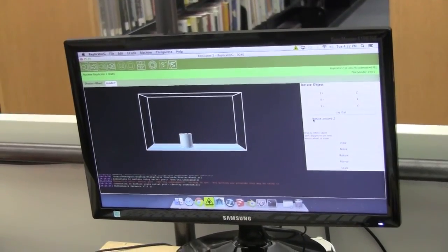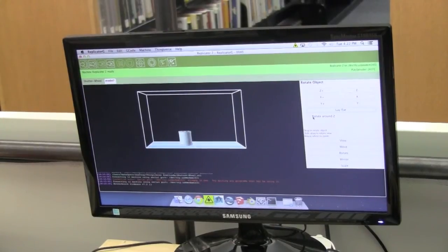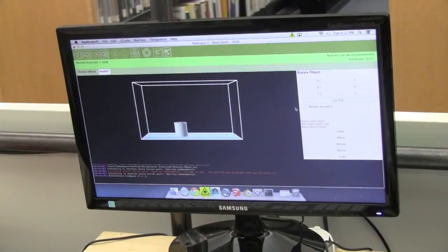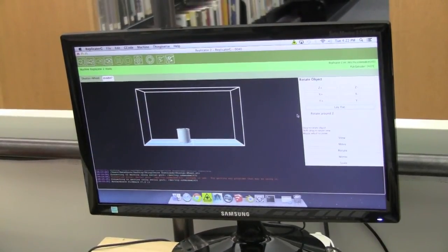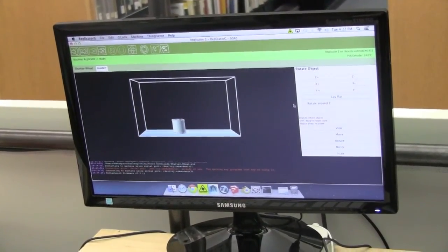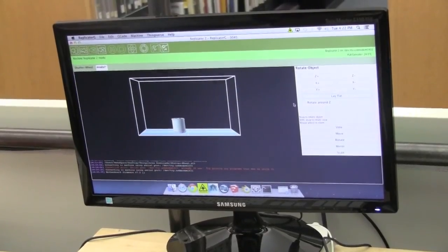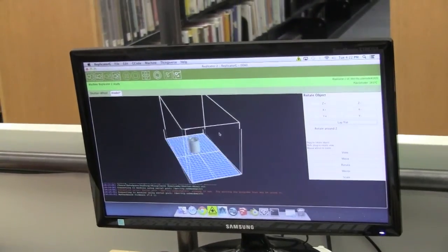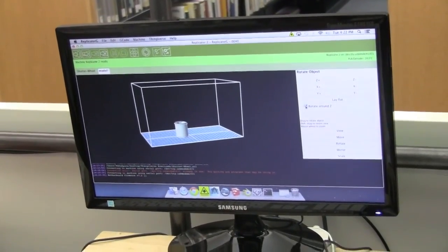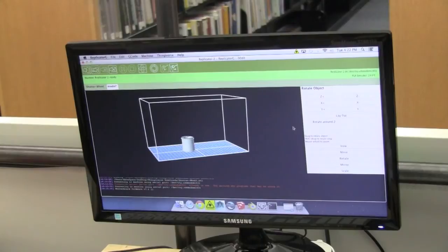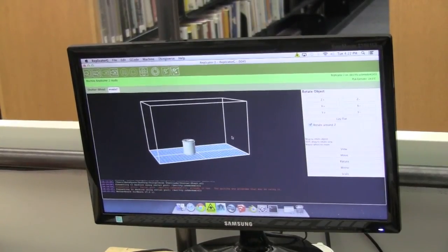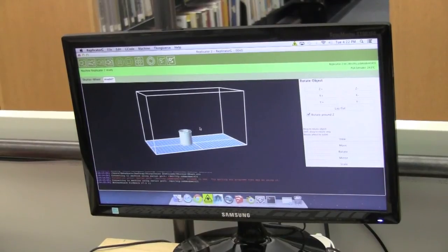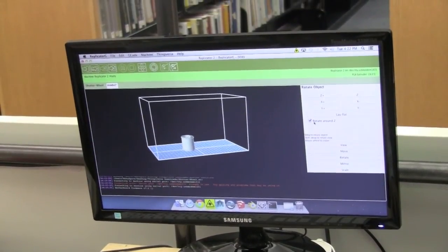Also, just to go back, when a designer makes something, in all likelihood, is it in a position that's good for printing? Yeah. It should be flat or on its side, but it shouldn't be at some angle that's not 90 degrees. Yeah. And then next, instead of clicking and dragging, which puts it at some weird angle, you can lock it to rotate around Z, which means you can only spin it, but at least this way you're not changing the angle. Right. So that's that.